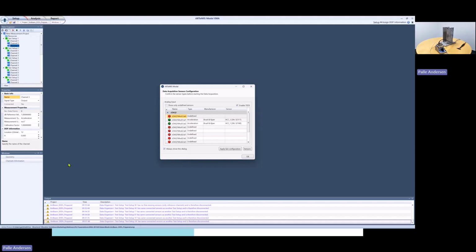All the sensors that are of a type with TEDS information, that means it has this built-in calibration, can automatically be read and configured. And you can see this is the case for the 2 accelerometers. They are already green here, showing that they actually have been identified, and we have read all the calibration information, so everything is good there.